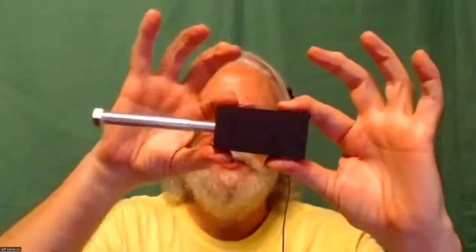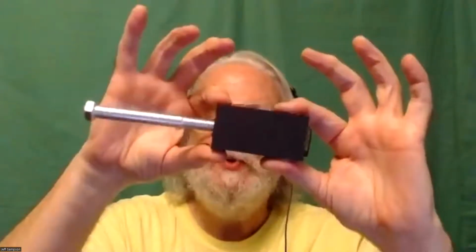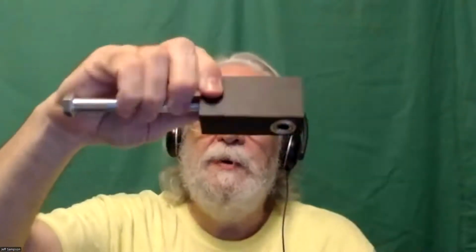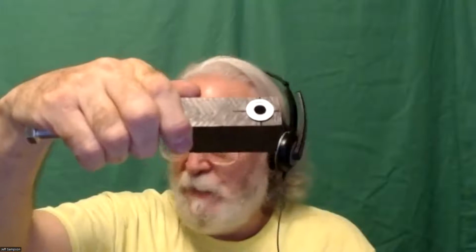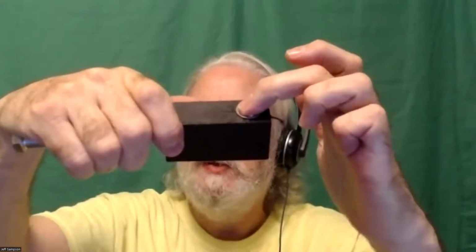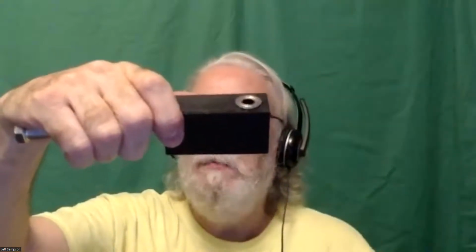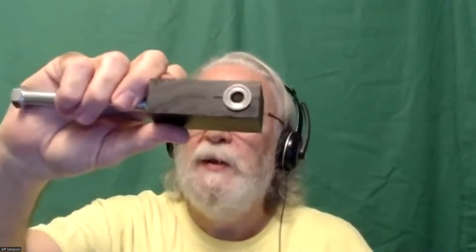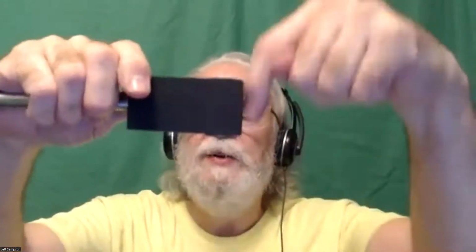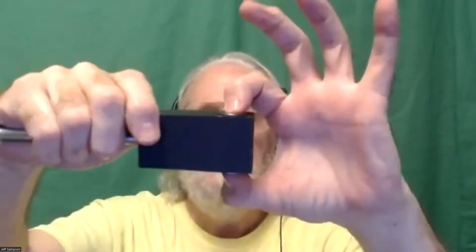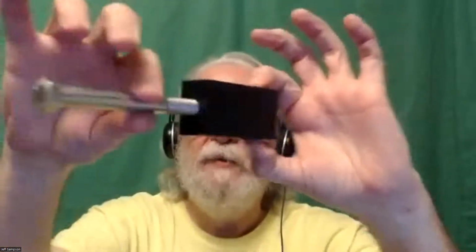And then my thought was I'd have it pivot around like this. So I drilled down through here and put bearings on both sides. These bearings happen to be metric bearings, so the center hole is 8 millimeters and the outside was something like 20 millimeters. But it turns out a 5/8 inch drill bit works just perfectly to do that. So I just ran a 5/8 inch drill bit down through it and then pressed the two bearings into it. So now if I have a bolt here, this thing can swing back and forth like this.